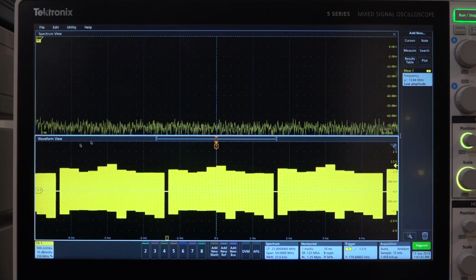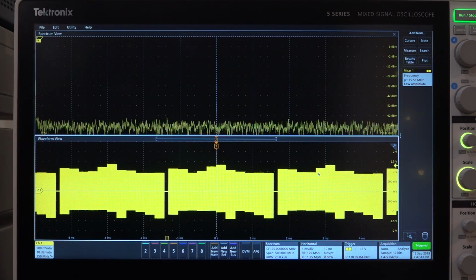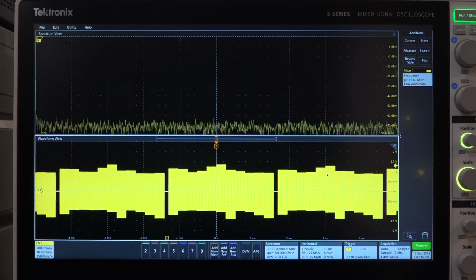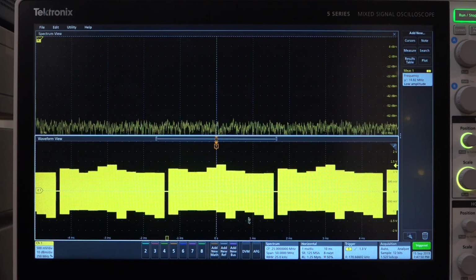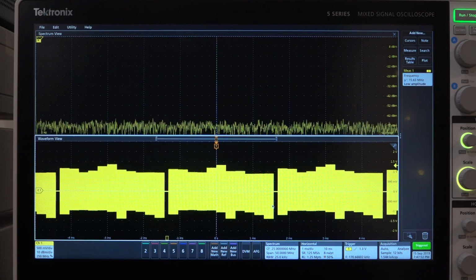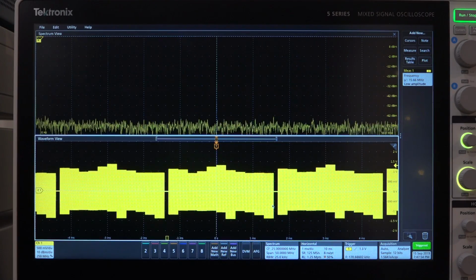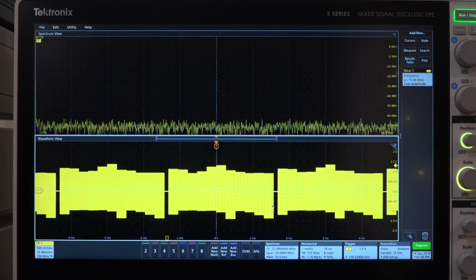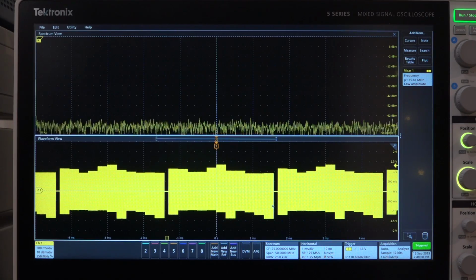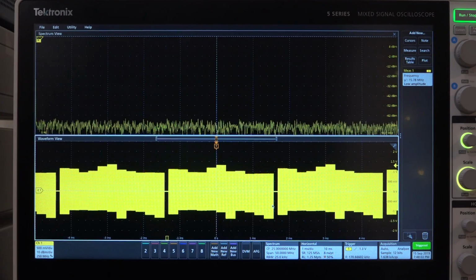Now you can also see some amplitude variation, or I should say apparent amplitude variation. That's not actually from the instrument itself. This has to do with the fact that the sampling rate of the oscilloscope has been reduced to 125 megasamples per second, just so you can get some rapid captures there, but you can increase that, and of course that would go away. The waveforms are perfect. We still have enough sampling rate, which we shouldn't have any issue in measurement of our signal there.